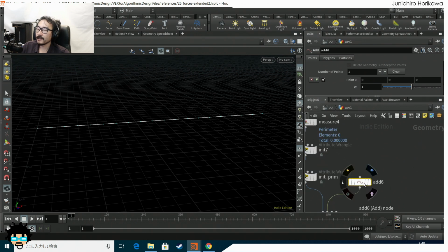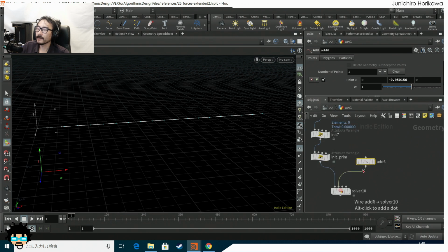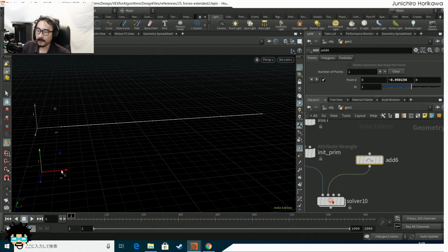And by changing this point position, I want this endpoint of the string to be stuck to this customly moved point by this handle. So if I move this handle, this point will always be fixed to it, and then the final result of the object will change depending on its position. Now that might be interesting, so let's try to do that. I'm going to set this to 0, 0 for now.